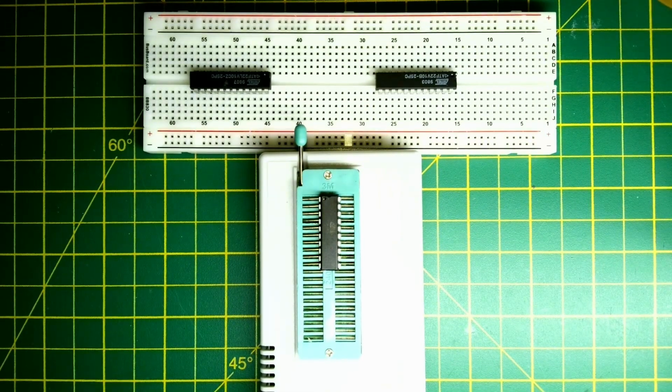So in this video, we've gone through looking at the documentation and showing that WinCUPL could run quite successfully on Windows XP, looking at the Windows help, looking at all the documentation. We've gone through in a fair bit of detail the ATF16V8B, which is a bit more complicated to configure just because of the different modes it has. And we've shown able to program it, and we've programmed it in the registered mode as well.